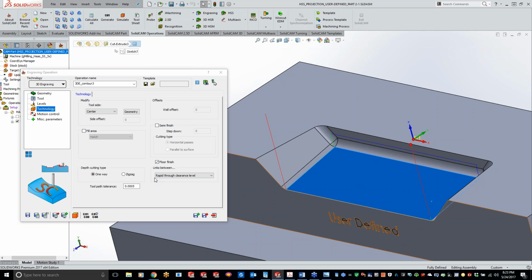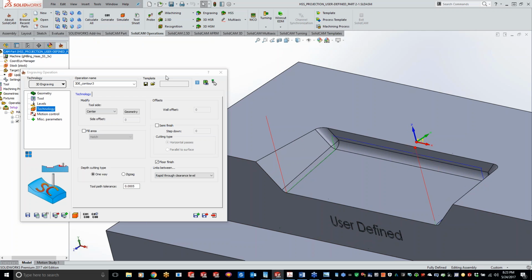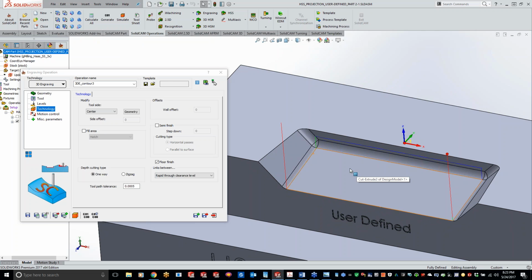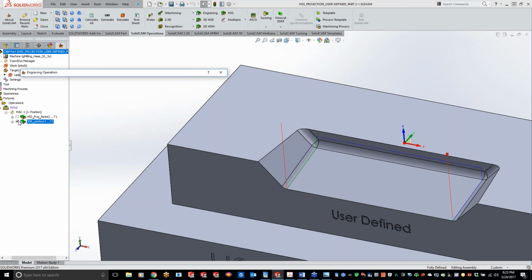But to answer the question, you guys will see we don't have any gouge check. If we get into something really complex here, do a check surfaces and do your drive surfaces with a gouge check, or your tool and holder collision, keeping your links down. You'll see right here, we're picking the exact same geometry from one to the other, but one is staying down, working how it's supposed to, and the other one's hopping up in the centers there.